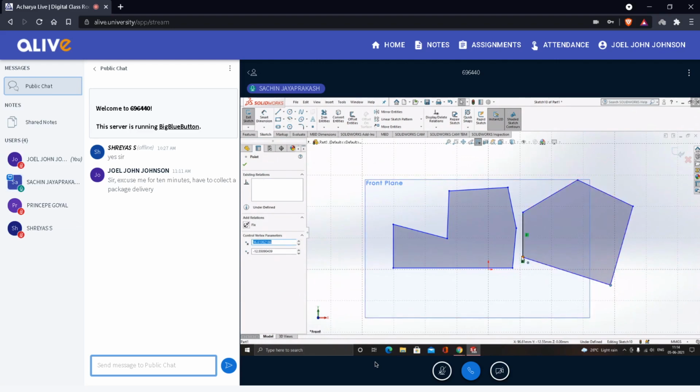Again, so now this line is fixed, so I can't move this point as well, this line. So this line again, it goes in only vertical direction, no horizontal, because this point and this point both it is fixed because of this line. So now we'll select this line and we'll fix it. Okay, so now this line is also fixed. I can't move these 2 points also. Okay, so it moves in only one direction. So this will not move only because both the constraints are there. So this will not move. So this, because this side is free, so it will move only in this direction. Okay, so similarly, I select this.